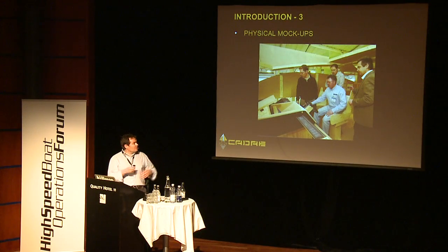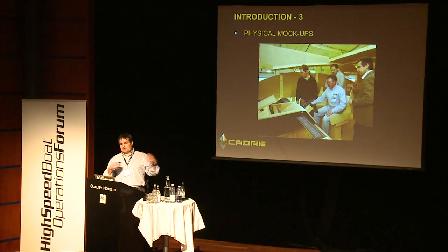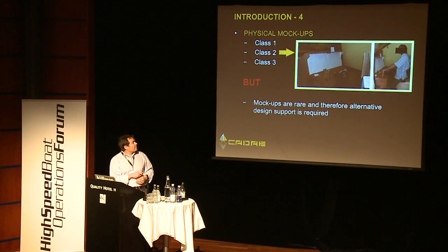Mock-ups are used, not as much as they could be, but even then when people build a good mock-up, so this obviously took an awful lot of time and effort to produce, but if you actually sit in this seat, can you actually operate all of these effectively? If you're sat in a mock-up and you're already leaning forward to operate this, it would suggest that some modifications are probably worth making. So just because you build it doesn't mean to say the boat couldn't be better, and how do you actually do some of that analysis.